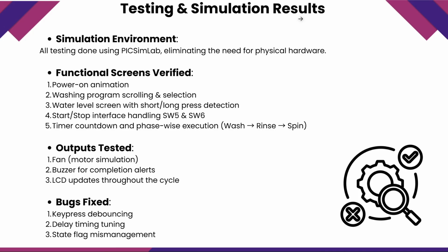Outputs tested: first, fan for motor simulation; second, buzzer for completion alerts; and third, LCD which updated throughout the cycle. The bugs fixed were: first, key press debouncing; second, delay timing tuning; and third, state flag mismanagement.